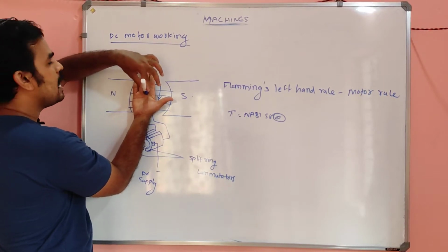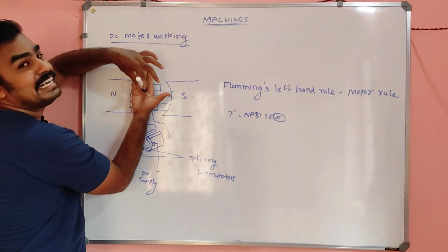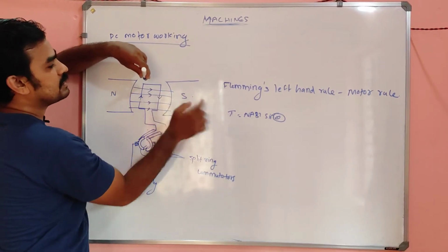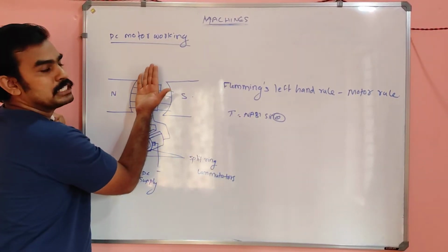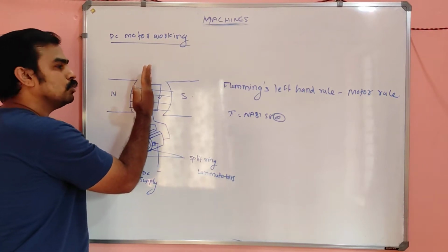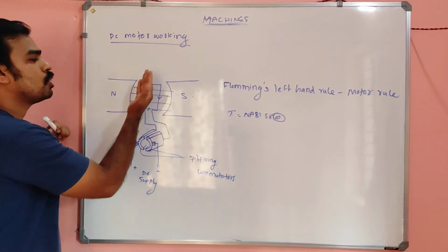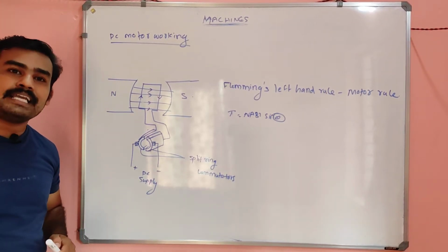So this is the line and the lines of force, my dear. So what will be theta now? Theta will be now 90 degrees. So this is the flux line direction, this is the perpendicular direction. So in this position only, torque will be maximum. When it comes to here, and here, what happens? The torque will be zero. So the coil will try to stop by itself.